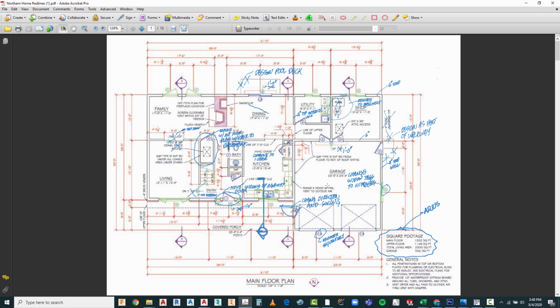Here, our garage is actually a slab that is going to be resting on grade. The top of it is at -1 foot in relation to our benchmark elevation. For this one, we're just going to give it a thickness of 4 inches. The same thing is going to apply here for the covered porch in the front. So one of the first things we need to do is establish where the edge of our covered porch is going to be. What we can do is use some of these dimensions.